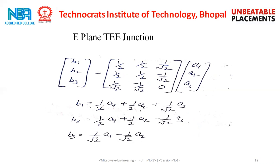So this is all about the E plane T junction. Are you all getting? Student, this is the E plane T junction, and this is the scattering matrix of the E plane T junction. Up till now, I have discussed H plane T junction and E plane T junction. Now I am going to discuss the EH plane T junction. This is the reflected column matrix corresponding to reflected elements. This is the scattering matrix, and this is the column matrix corresponding to the incident elements.